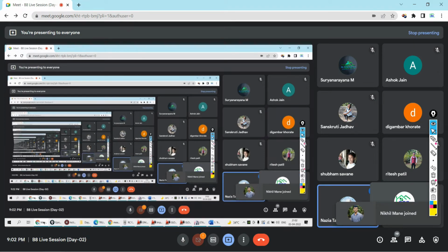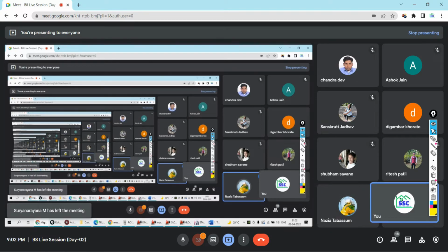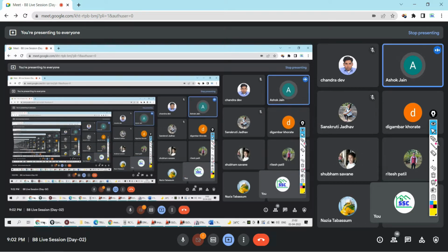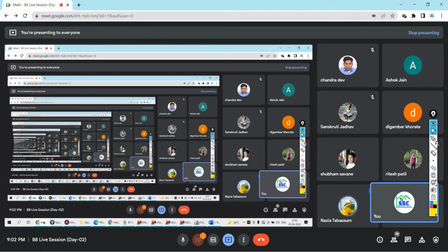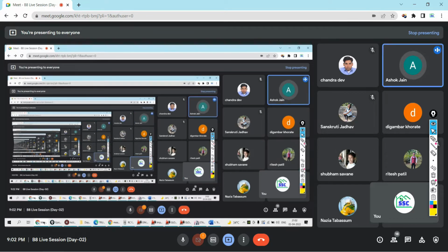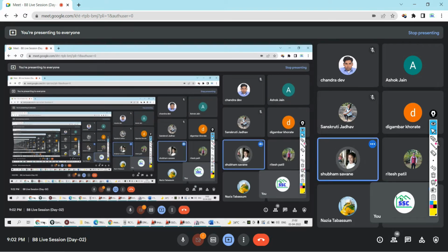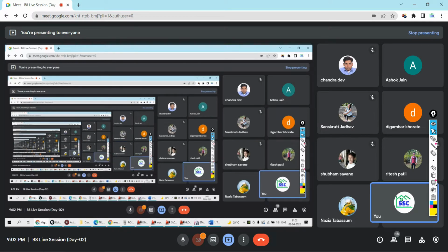Determinate truss or indeterminate truss? No, there are some assumptions. Members can carry only axial forces, tension or compression. All the joints are hinged. All the loads will be at the ends of the elements, at the joints only. All the members are connected at their ends only. All the members have a uniform cross section. Self weight of the member is neglected in the analysis.